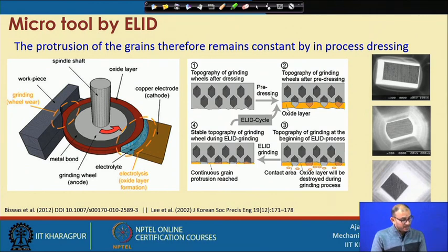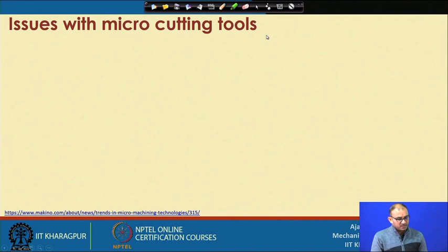because we have seen that in grinding there is still physical contact, and because of that you can see this is 100 microns. The diameter of the bigger side is more than 200 microns or something like that. Similarly here the dimension is 100 microns, and this may be considered 70 microns or something. Going down and down is very difficult, but still this is a reasonable size of cutting tool which can be fabricated by the ELID process. Right. So, these are the different processes.